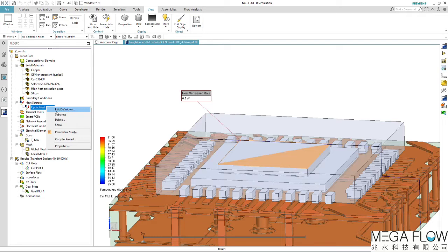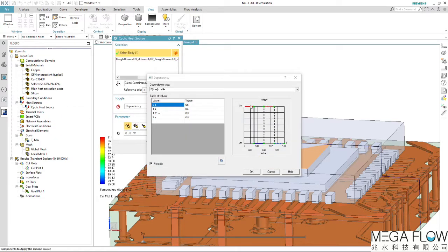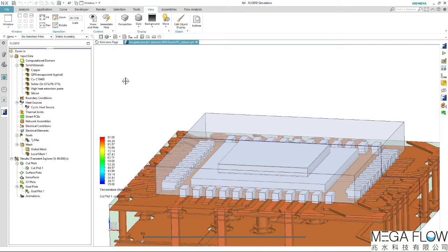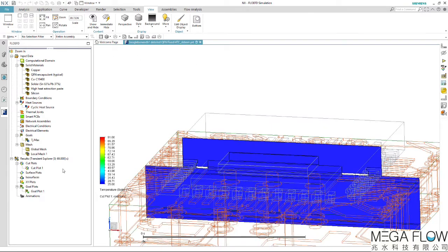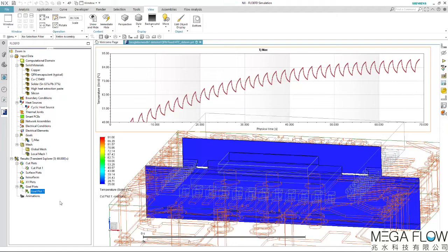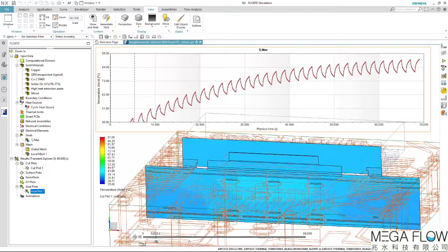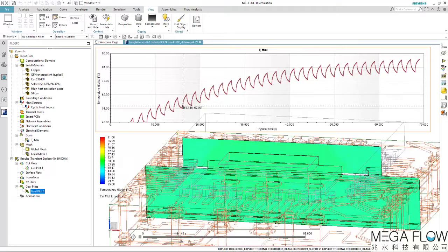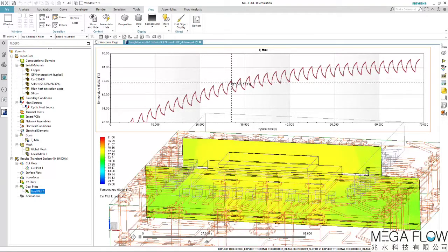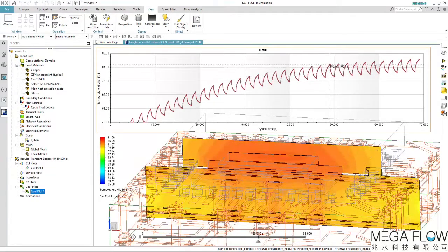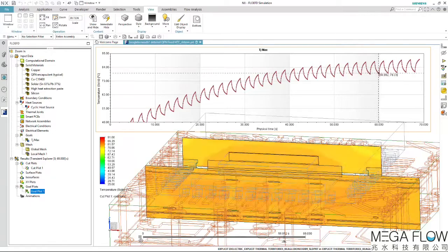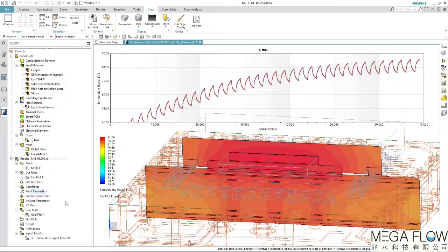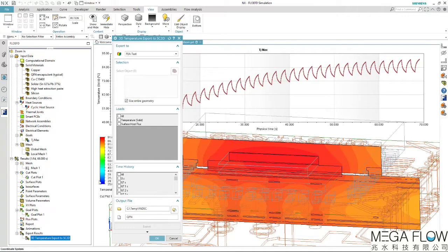The QFN power dissipation of 0.8 watts is cycled with a period of 2 seconds and a transient thermal simulation conducted. Sufficient power cycles are simulated until such time as the thermal response becomes periodic. Once this is achieved, the full transient 3D temperature fields of the final cycle response are exported to the file system and converted into a format for direct seamless import into SimCenter 3D.